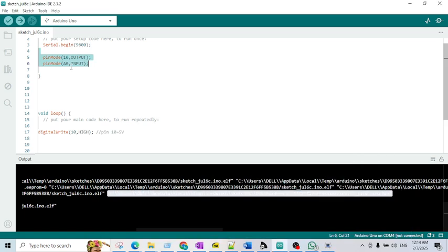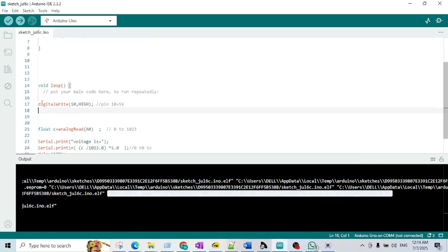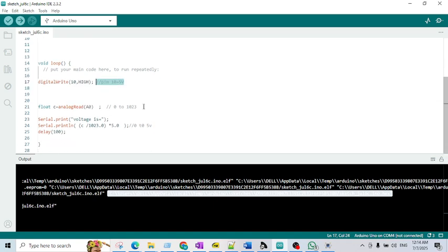And then we have set digitalWrite pin 10 high, that means pin 10 will supply 5 volt, and we have read the data from A0, and A0 will give you the data from 0 to 1023, but you want the data from 0 to 5 volt. So to convert 0 to 1023 to 0 to 5 volt, you have to do a simple calculation here, right?